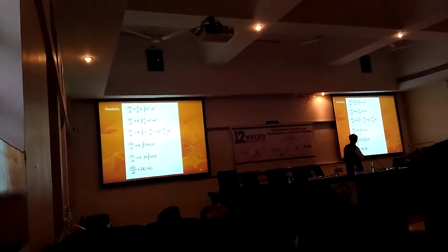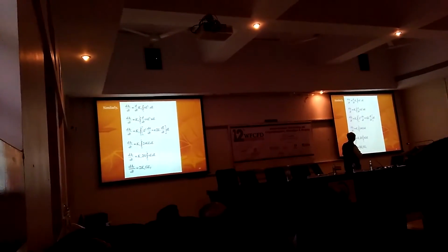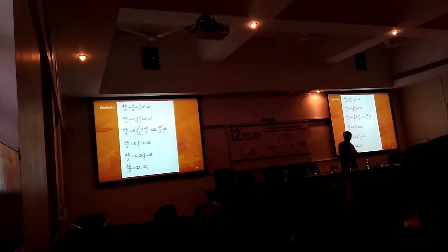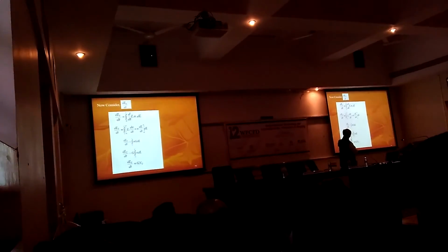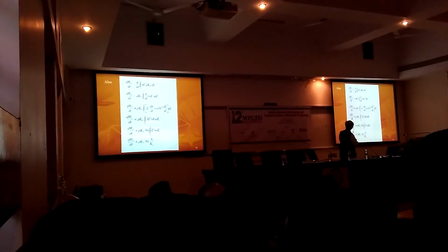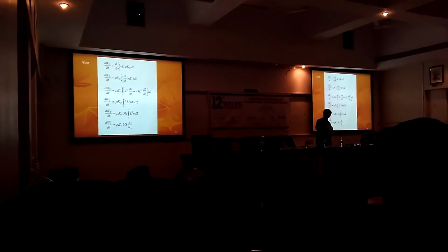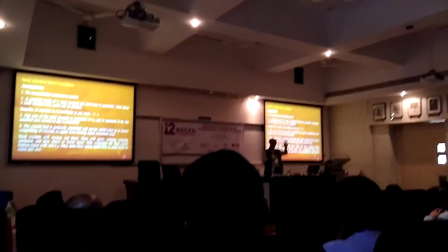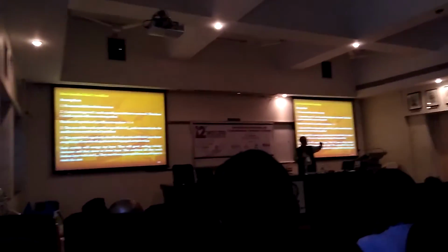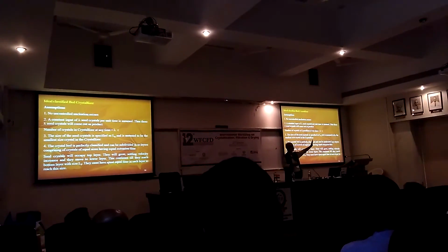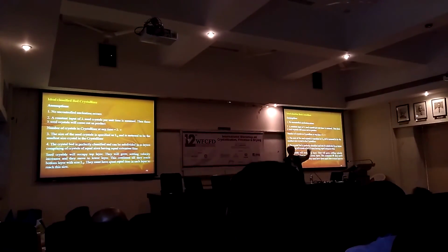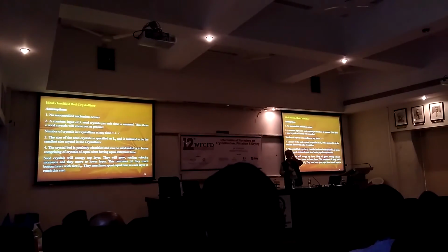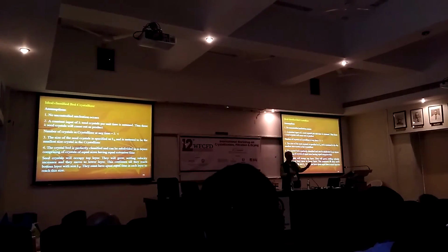Depending on the case, you calculate different moments of the distribution, and the moments will tell you total growth, total increase in length, area, and volume or mass. All this can then be integrated effectively to give a crystal size distribution and also the quantum of crystals which you are going to get. So mass recovery on one hand and recovery in the form of crystal size distribution on the other hand, both these objectives are effectively met.